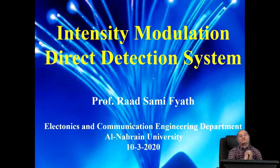While for synchronous or coherent detection, we must use a local laser in the receiver side, operating synchronously with that used in the transmitter side. This is used for single sideband AM signals and for double sideband suppressed carrier AM signals.